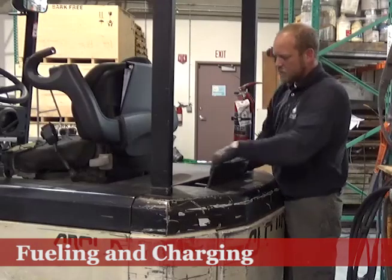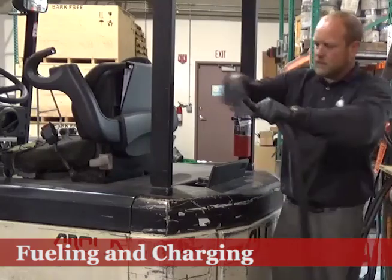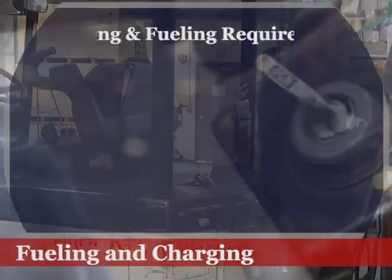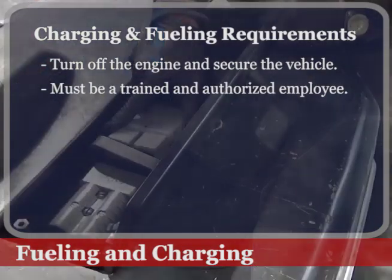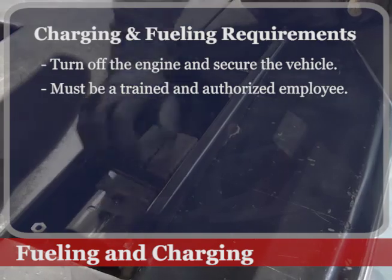Forklifts will require frequent recharging, or refueling. While each forklift will have its own special procedures and requirements, here are some basic safety rules to keep in mind. Turn off the engine, and secure the vehicle, before charging or fueling. Recharging and refueling should only be done by trained and authorized employees.